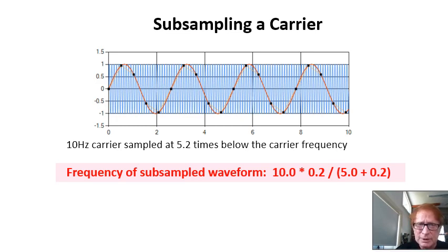Direct RF digital subsampling to arrive at a sampled reduced frequency perfectly preserves the amplitude and phase information stored within the modulated carrier and inserts no nonlinear operations. However, can subsampling be accomplished in a practical radio mechanization? Direct sampling the carrier is the goal for all software-defined radio, or SDR.